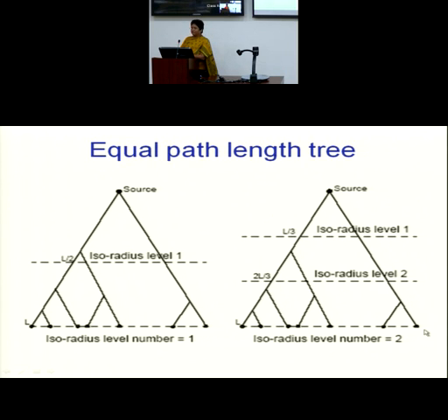Still again compute the skew, and if it is still not coming within bound, increase the cut lines. So the normal approach is this, where we follow the equal path length approach. This is how we determine, in a very simple way, the buffer insertion points.